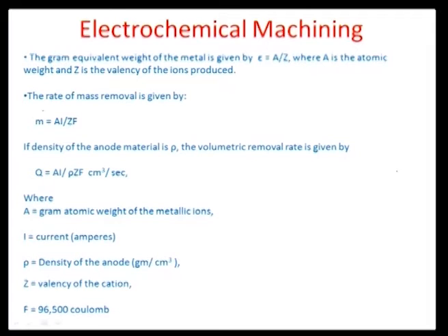As you already know, by Faraday's laws, the amount of weight in grams of a material dissolved or deposited is proportional to the current, the total time duration for which this current flows, and epsilon, which is the gram equivalent weight of a material.